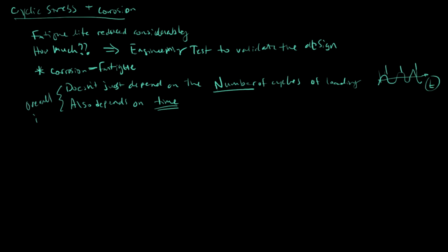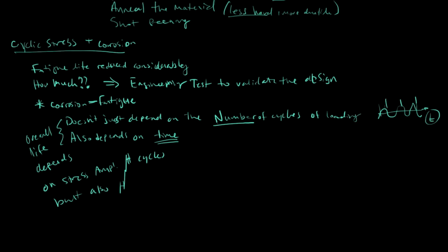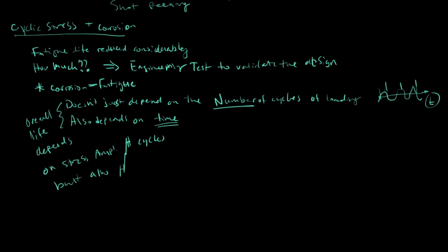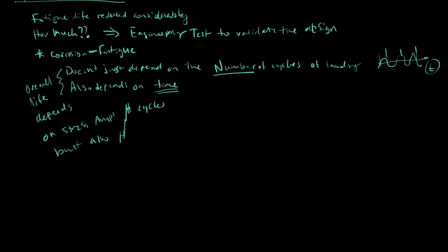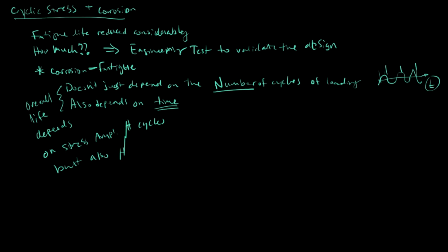So the overall life is going to depend not only on the stress amplitude and cycles, but also how long the material was exposed to that environment.